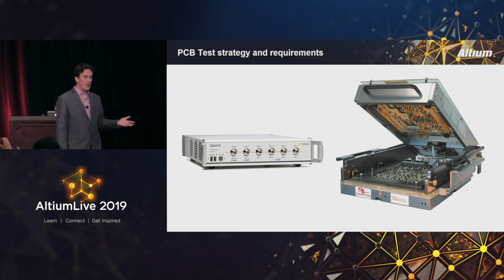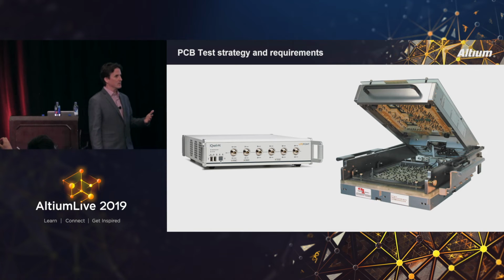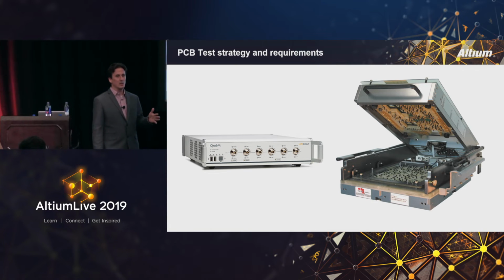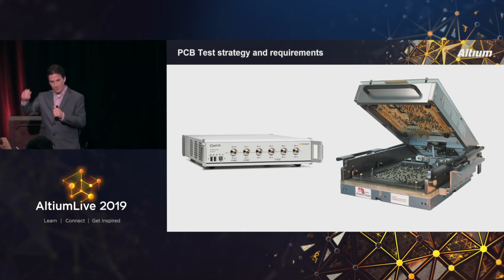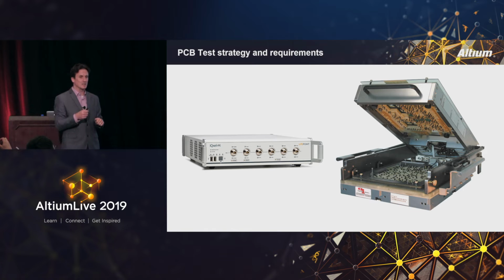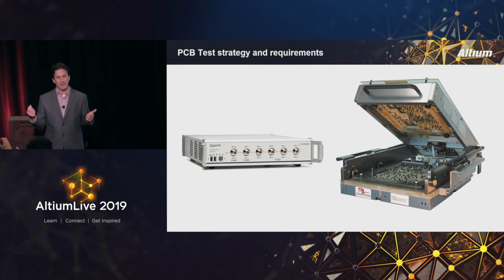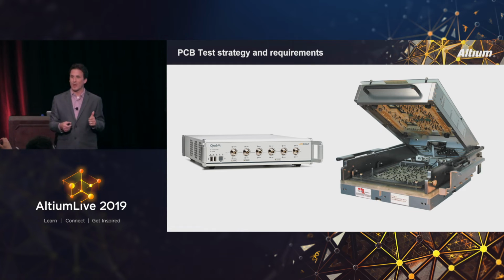And when you're using a bed of nails, ideally you want your test points on all one side of the board. Now they can make beds of nails that come down on both sides of the board. Again, way more expensive, less reliable, wears out quicker, needs more servicing.